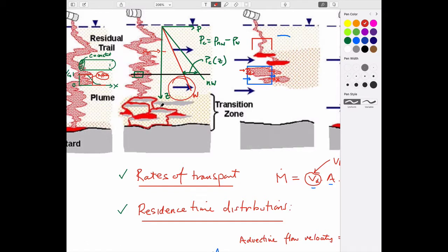We will talk today about contaminant transport some more. Last time we made the case that the mechanisms by which transport occurs are diffusion and dispersion. Diffusion being molecular diffusion, Brownian motion, which is quite a slow process, similar to diffusion of odors, if you like, in air, but in water in this particular case.